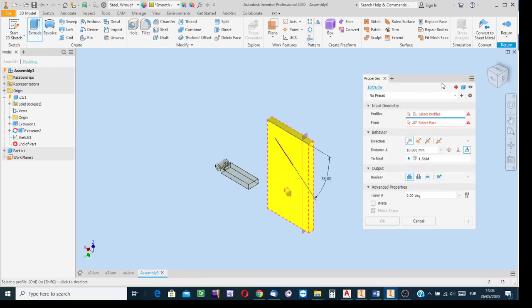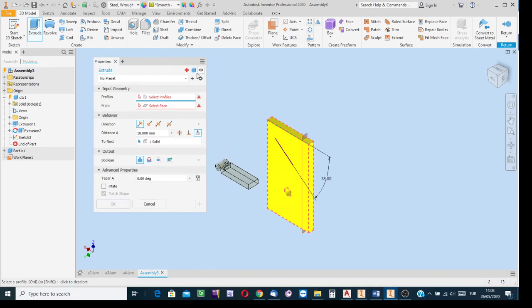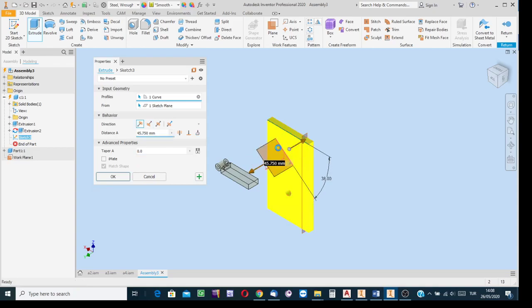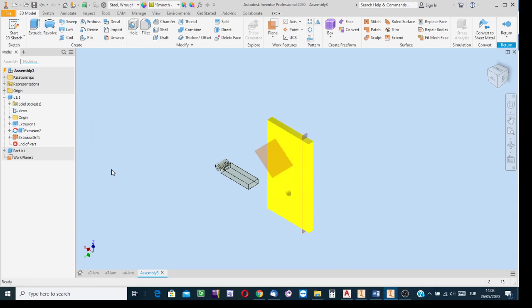You know the trick. In the dialog box, do not select solid model creation option, but surface creation. If you clicked on this button, then you can apply extrusion process for creating surfaces. Indicate the sketch and then have a work plane. Yes, the size of the plane is not so important.